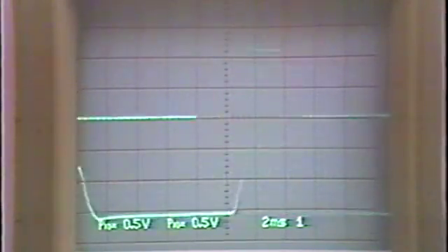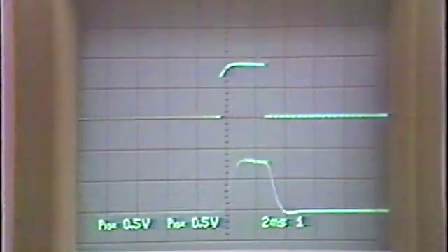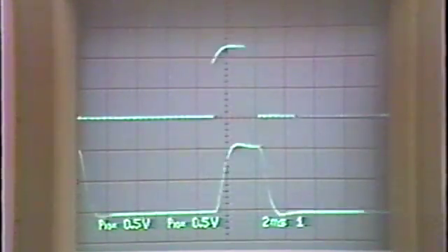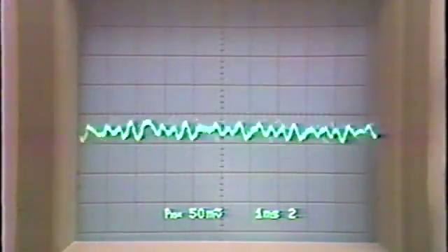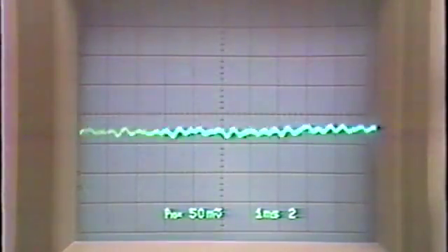The bass signal enters the filter where the square waveform of the pitch signal is converted to a triangular waveform. The waveform at the bottom is filter output. Chord sounds are created in the same way, but since they are combinations of 3 or 4 sounds, the sound is created by mixing 4 pitches and 4 envelope signals. This is a mixed chord signal. Next, we will explain how percussion sounds are created.